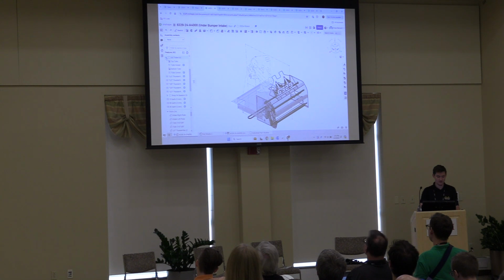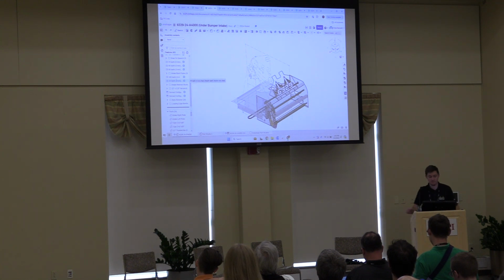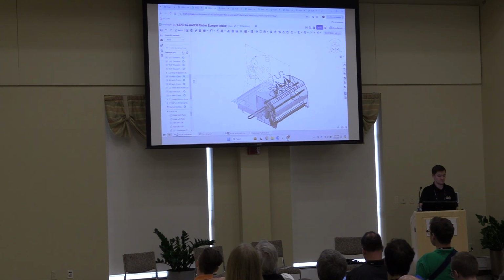to keep everything together. And of course, the rollback bar, the way that works is, this is essentially just an equation that is building out step by step to create these parts. So if I wanted to go back and change these snap-on spacers, I would not want to just start sketching and making new features because then it's going to end up at the bottom. But it was referencing everything else up here. So what's the best practice to do is open up that folder, right-click, roll to here.